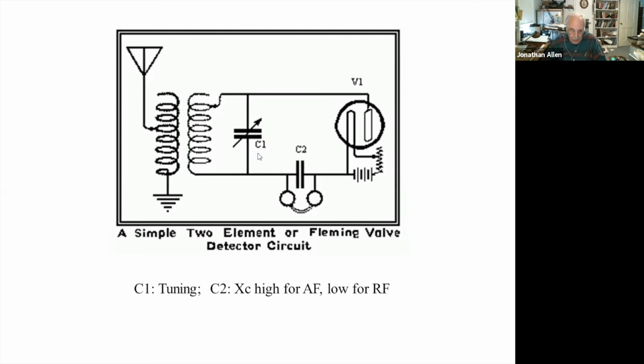In that same year, a fellow named Wehnelt in Germany found that coating the thermionic filament with either calcium oxide or beryllium oxide could increase the emission, that is, how much current of electrons you could emit. We now know that thermionic emission occurs when the thermal energy of the most energetic electrons exceeds the binding energy that holds them to the conductor, and we call this binding energy the work function of the cathode. The coatings reduce the work function and therefore allowed more electron emission. We'll get into this more a little bit later.